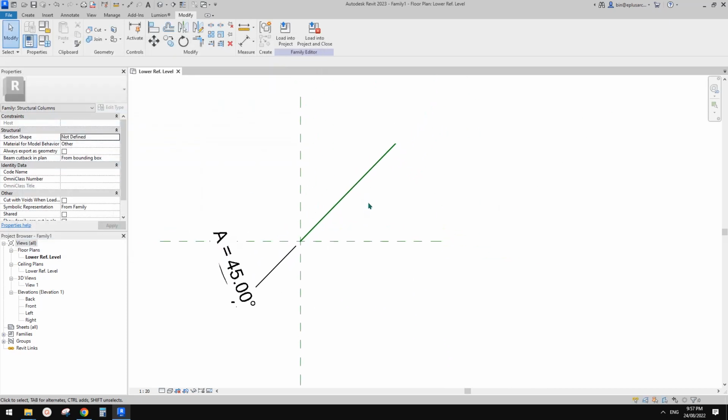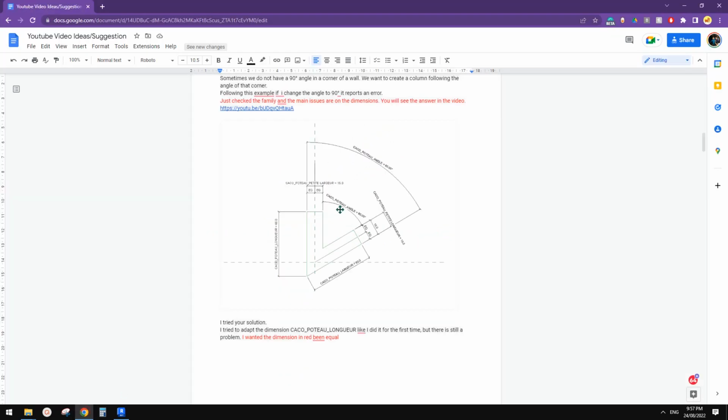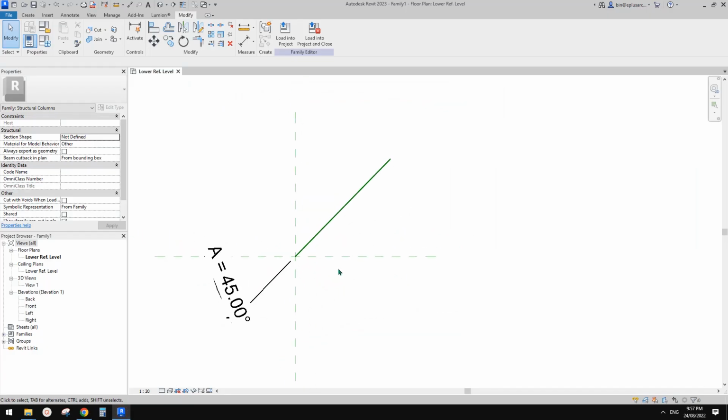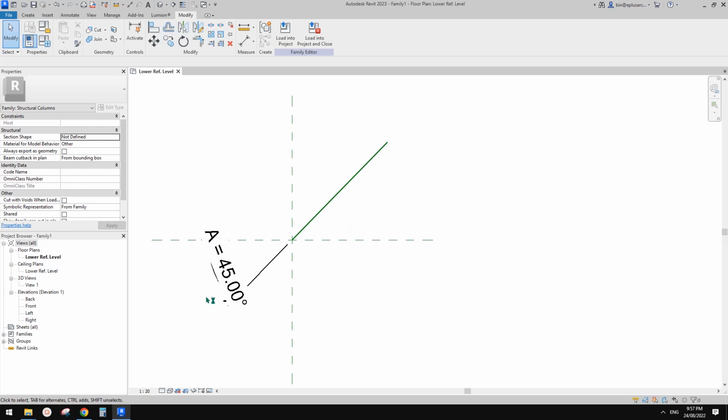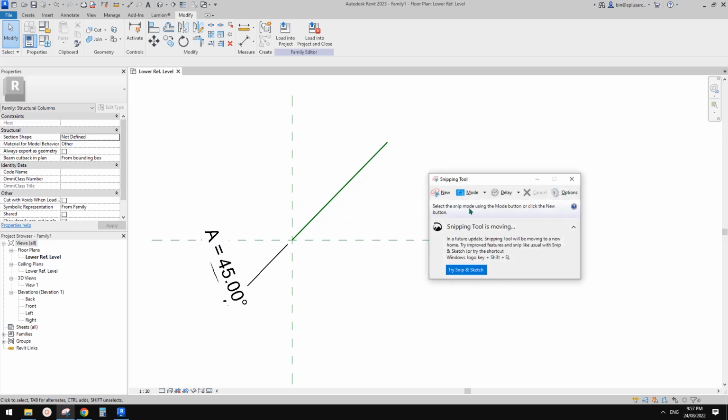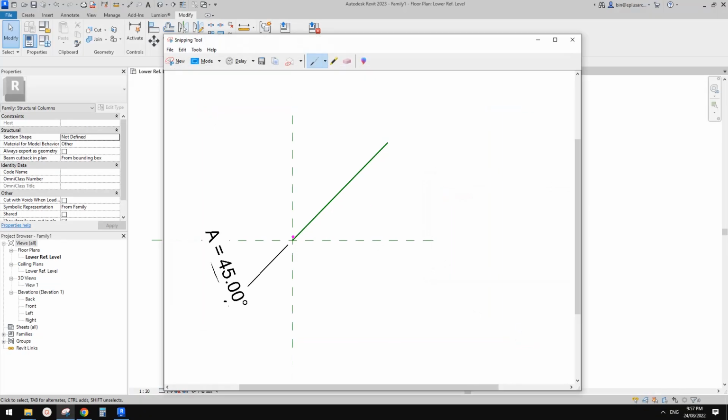So the next step is we're going to create this. I'm going to use extrusion for this. Let me think. Okay, so I'll just do a screenshot. And with this extrusion, this family will look like this. So this edge can be locked onto this reference plane, and this one the same, so we just need a dimension, and this locks onto this reference line, and then for this we need another dimension.